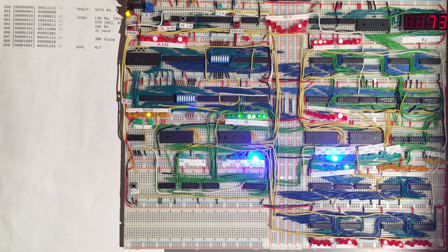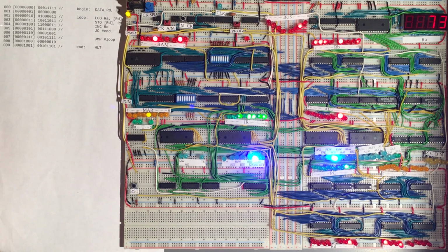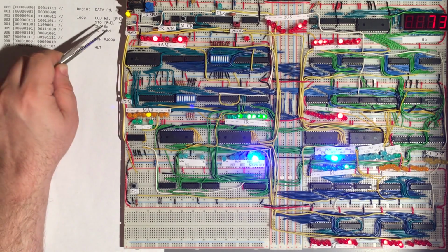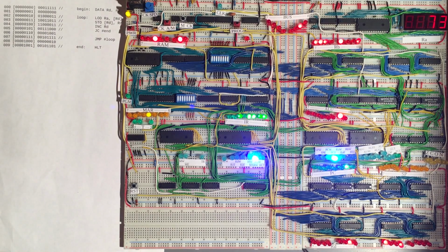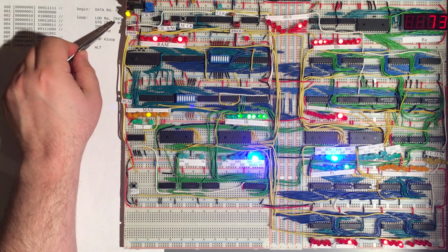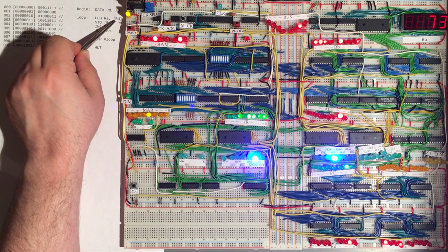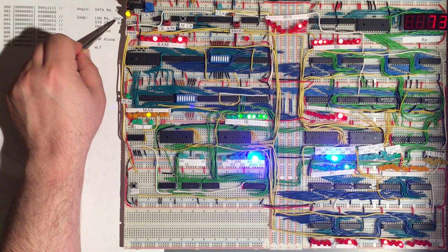Now, at the moment, the program counter has a value of 2, and our micro timer here is at time t0, so we're just about ready to start executing the instruction at address 2, which is this load instruction. What that's supposed to do is to look at the D register, which is down here, and currently contains a value of 2, and it should use that 2 as the address in RAM, and so read the byte which is in data memory at that address, in this case 2, whatever the contents of that register are.